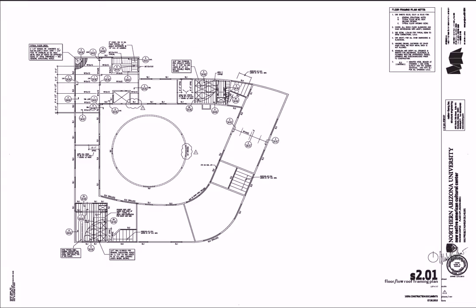I'm going to go to the next page here. You can see this says framing plan. So framing indicates that it's structural. So I might concentrate a lot down here on the titles of the pages. You can see right below here that these were issued for 100% construction documents, so I expect them to be complete. This has floor and low roof, so I'm looking at this saying,